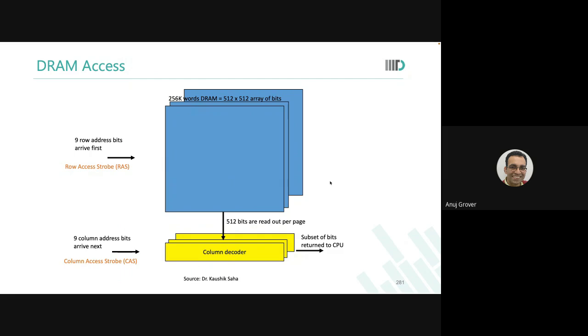Also, generally because of the locality of reference, all the bits of words are arranged sequentially. So if we select one word by RAS first, then the whole row is open. Then when we send CAS, we extract the first bit, and we can continue to use CAS to extract the other bits of the same word because of locality of reference. But we cannot do the same if we send CAS first, because then we have to wait for the whole cycle to complete.